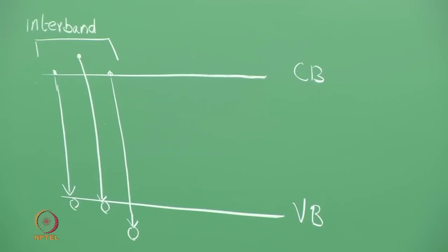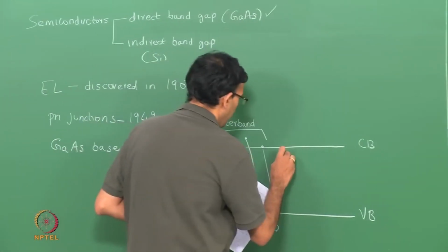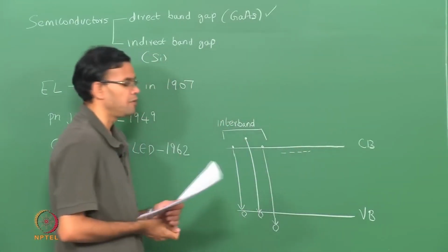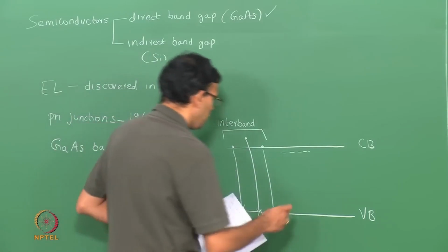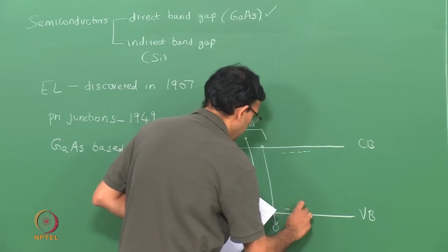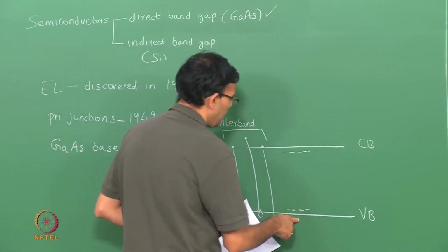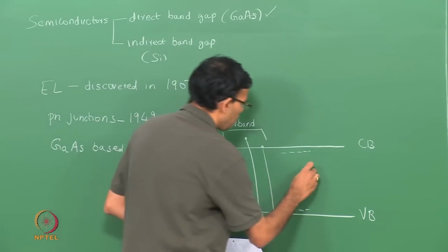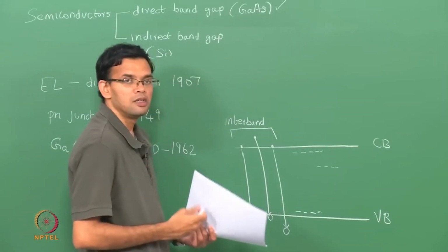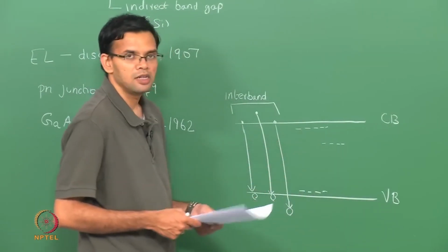Now, if you have a material that is doped or has some other impurities, these basically cause defect states in the band gap. So, for example, if you have a donor type impurity, that could lead to a donor level that is close to the conduction band. You could also have acceptor levels close to the valence band. These are essentially shallow states. If you have other impurity materials or other defects, they could also form states slightly within the band gap. So, these are shallow states, this is a deep state.